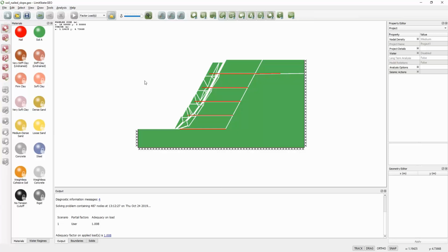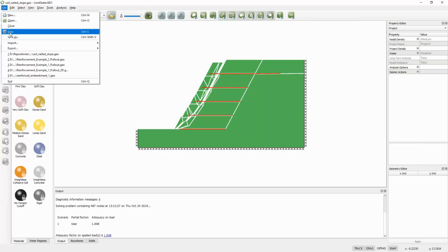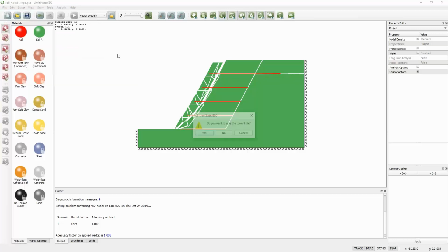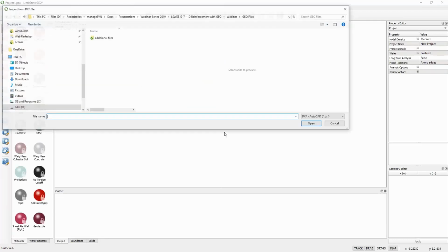Got a question about how we generated the models. Did we draw them by hand? There are various ways of doing that. If they're fairly simple, we've drawn them by hand, but you can draw them in a CAD package, and we have the facility, if I just show you here briefly, to import a geometry. I haven't got any in here at the moment, but we can import DXF files, and therefore for complicated geometries we'd recommend you generated them in a CAD program and imported them.